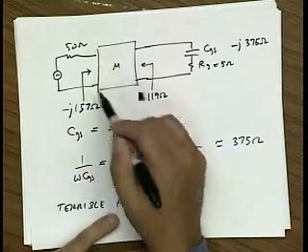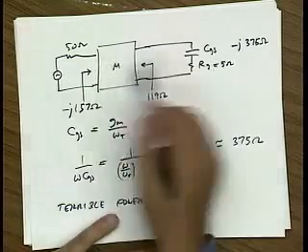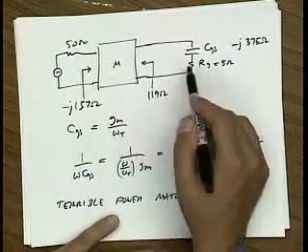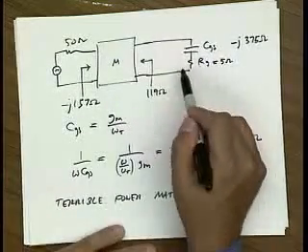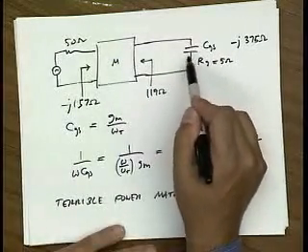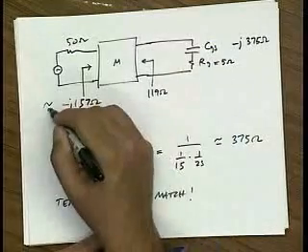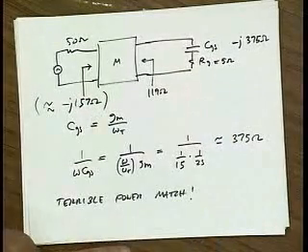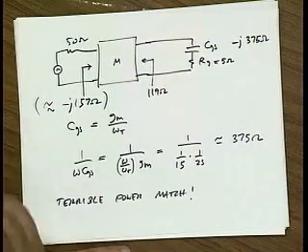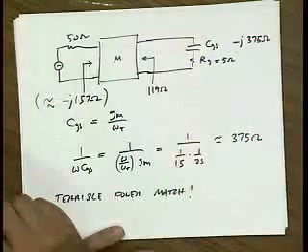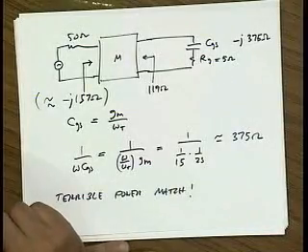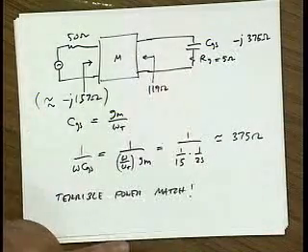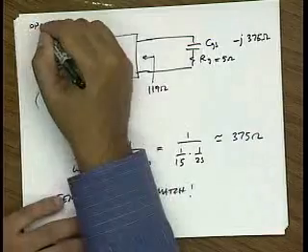And of course, I'm assuming this is an ideal matching network that just transforms anything you give it. In reality, we know that the matching networks we design are used to match real impedances, right? So this is really an imaginary kind of calculation. But the point is that you're not seeing a power match, and so your filter is going to have additional insertion loss, and you're going to lose a lot of signal because of this. So let's call this option 1.